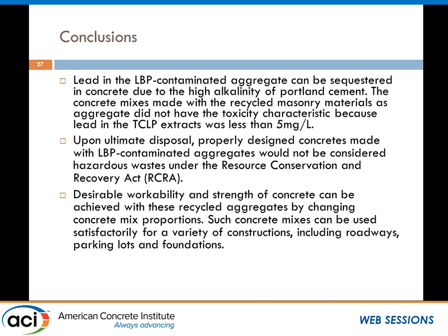First of all, we accept the 4 mixes with clay brick as masonry materials. Most of the mixes have the TCLP lower than 5 micrograms per liter. That means it's environmentally safe. The recycled aggregates we use will not be considered hazardous under the RCRA, the Resource Conservation and Recovery Act.